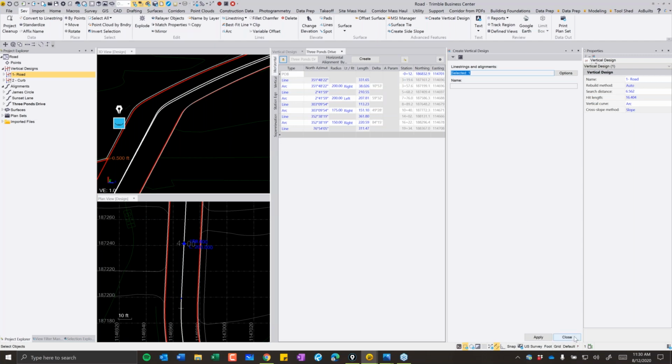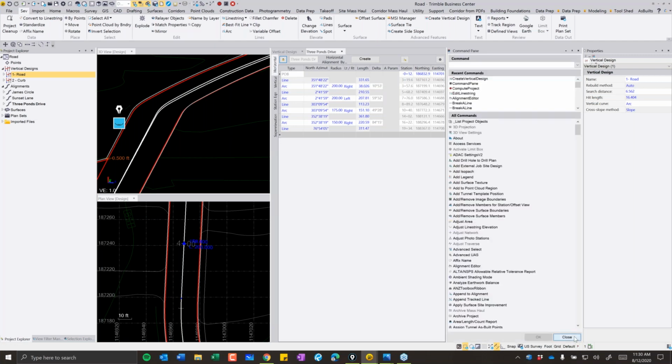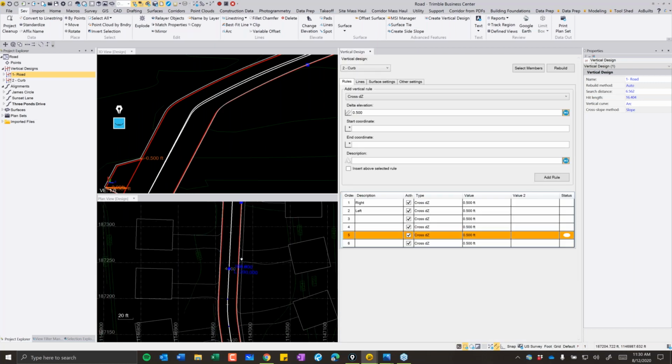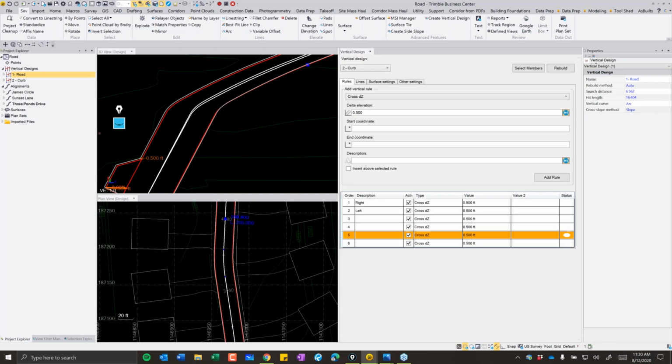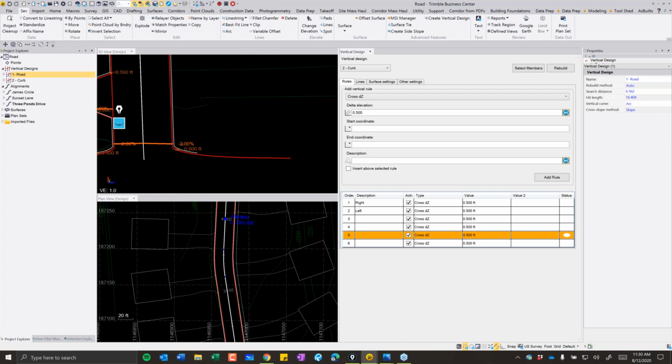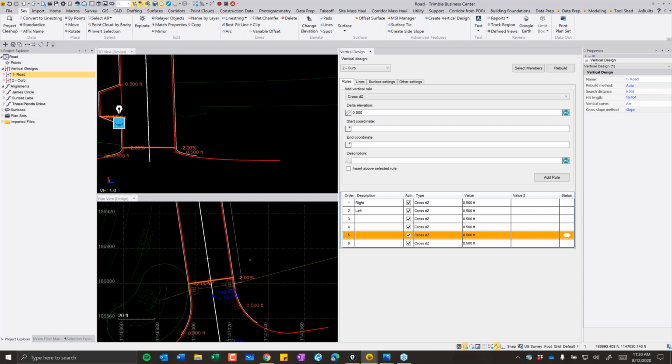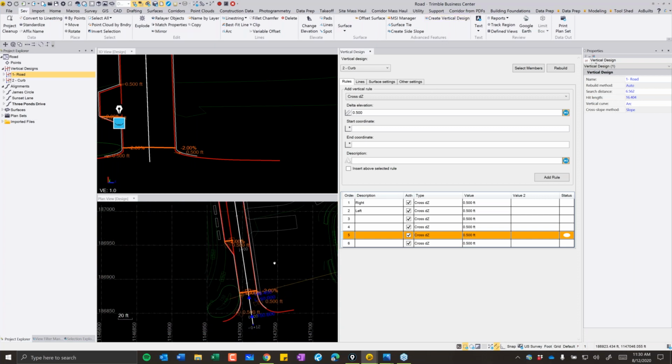But, so do you find in your modeling sort of daily work, obviously you're kind of a master of most of the tools that we have, like side slope and corridors and vertical design, and then just standard data prep and CAD kind of tools. Do you find that you build your models with a combination of those different tools to get to the end result? Obviously, vertical design doesn't have tie slopes, so you have to find a way of tying to the ground. So what kind of combinations do you typically find yourself using?